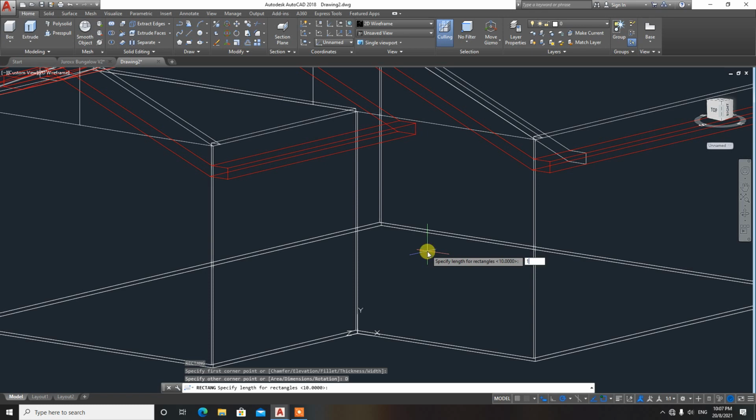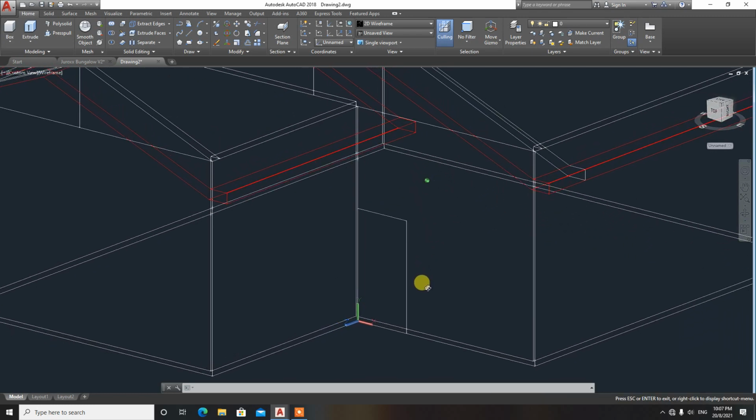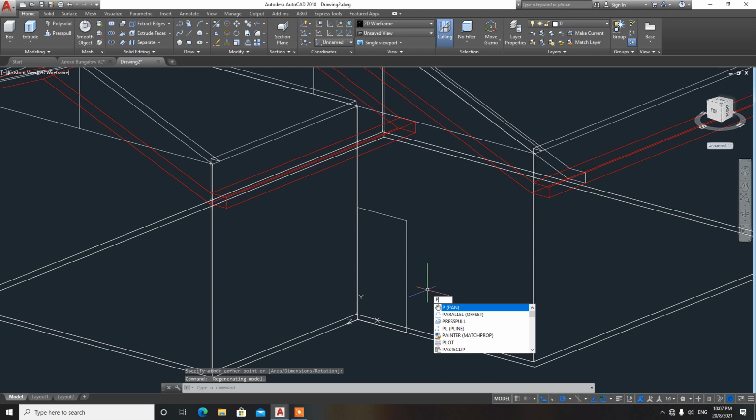In its length 1100, enter, and the height is 2100, enter. See whether it goes correctly or not. Click. After that, click. You can definitely use the press pull command to subtract or to create the door hole or cut out. So I'm going to use the press pull command to create a subtraction of